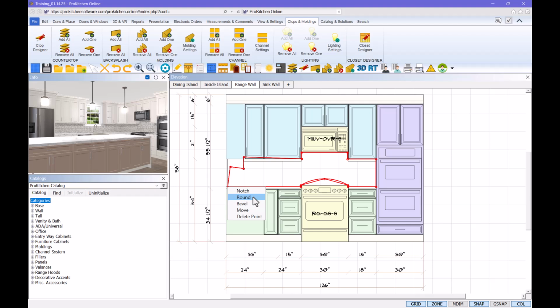Once you left-click to select, you may once again only create the rounded corner to the interior. As you move the mouse, you will see a preview of the rounded corner. Drag the rounded corner into place and left-click to secure. Once created, you will now have 2 points on either side of the curve that, when selected, will change the shape of the item, and a center point that will allow you to adjust the curvature of the rounded corner.